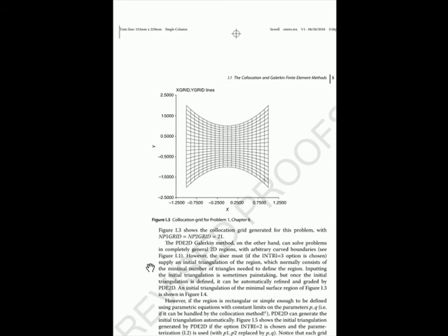The other main difference between the collocation and Galerkin method is the way two-dimensional regions are handled. So this is not relevant for 1D problems because they both just handle intervals A to B. And it's not relevant for 3D problems because there is no Galerkin option. So this is strictly a 2D issue. The Galerkin method can be used to handle completely general 2D regions.